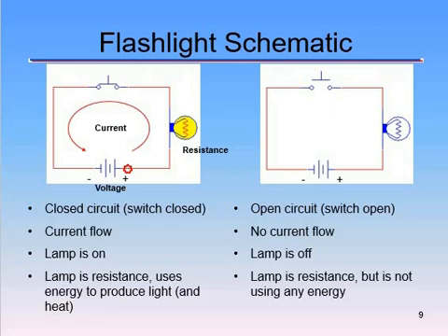So we say in that case resistance is infinite, and that's important later on when we start using a multimeter to troubleshoot. In the picture on the left, or the schematic on the left, the switch is now closed and current is flowing. When current flows and it has a complete path, those electrons turn on the light bulb. Alright, so this is called a closed circuit. The picture on the right obviously is called an open circuit because the switch is open.